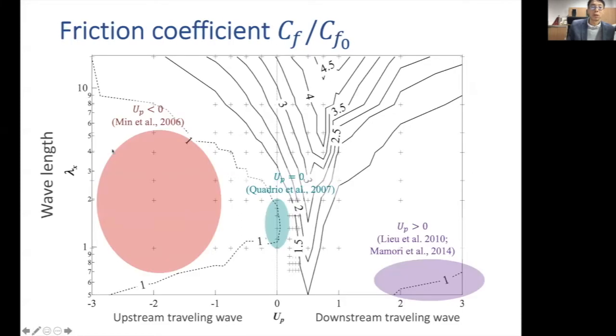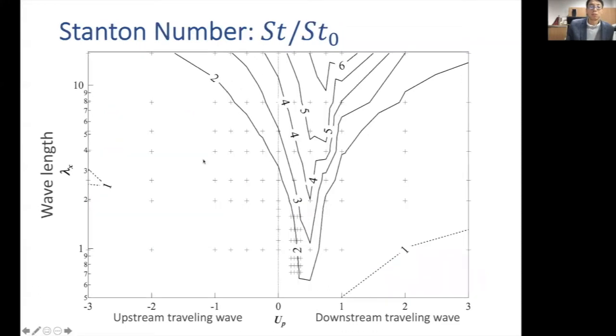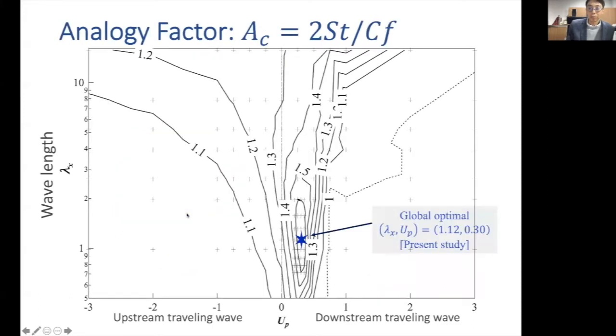So in the case of the pressure drop or wall friction, we have a smaller value than the uncontrolled flow. So we have a drag reduction, but the heat transfer is actually higher than uncontrolled flow. So here we have some sort of dissimilar effect already.